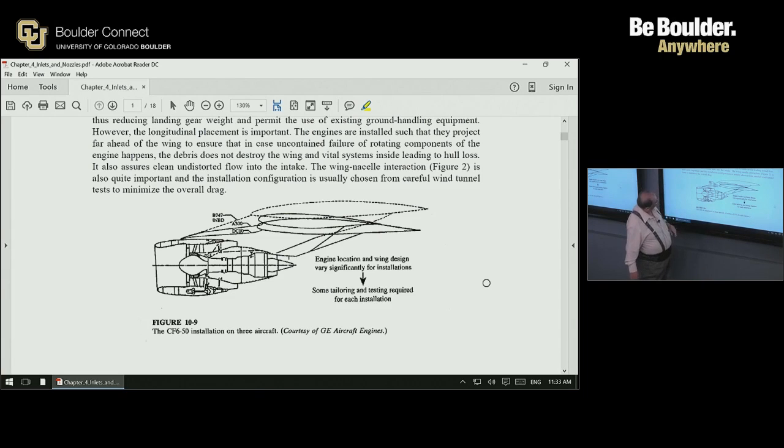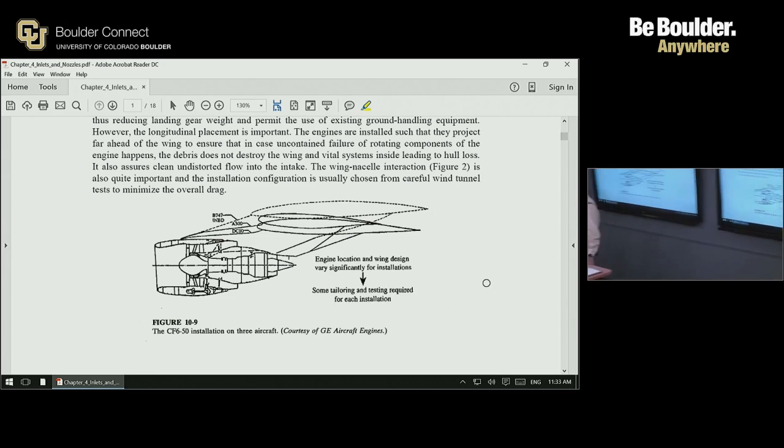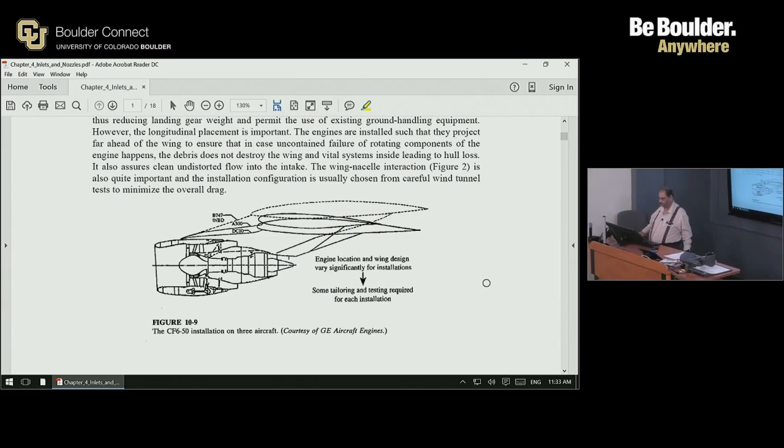Although, if you notice carefully, the inlet plane of the nacelle is tilted a little bit, about 3-4 degrees. That happens because the lift on the wing produces an updraft ahead of the wing and a downdraft behind the wing. And the updraft essentially changes the angle, and therefore you have to accommodate for that. So that angle is about 4 degrees. You can easily calculate what that is.